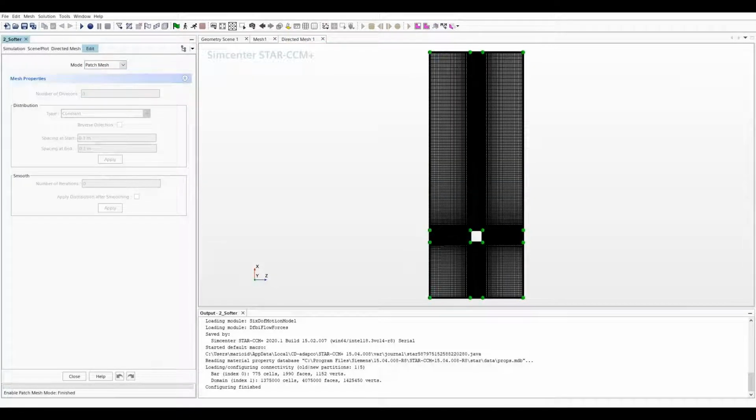First, let's have a look at the smaller segments over here, which have been specified as constant divisions. All these which you can see on the screen, which are highlighted, are constant divisions. But if we have a look at the other edges, which I'm going to select now, you can see that the type is specified as one-sided hyperbolic.